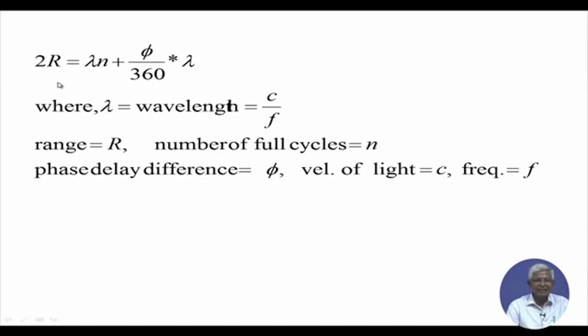But then you are sending a tone. Let us see, if r is the range, then 2r is many times the lambda that has gone once it has reached the satellite and has come back. So there will be many waves, n times lambda and a fraction of lambda. That is what you will be receiving.